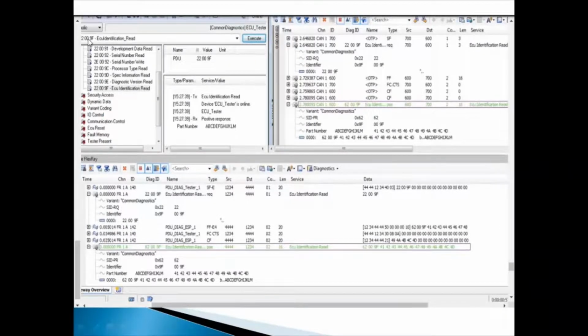Once you open that diagnostic console, here we are having the option, one space is there, where the raw value and all are mentioned. Here we are just entering the 10 service ID. Next, in this diagnostic session control we are having three subsections. The first is the default session, here, where the arrow mark is there.